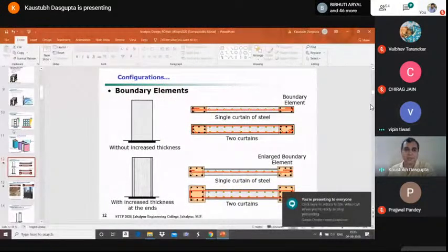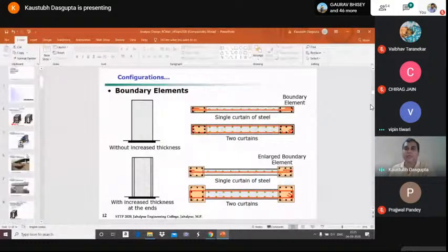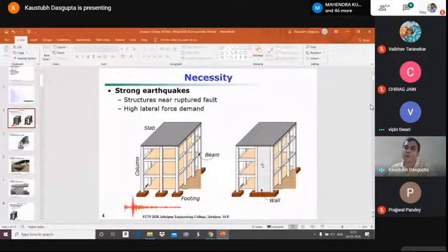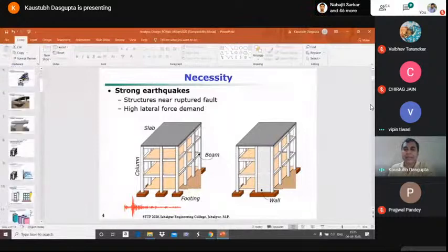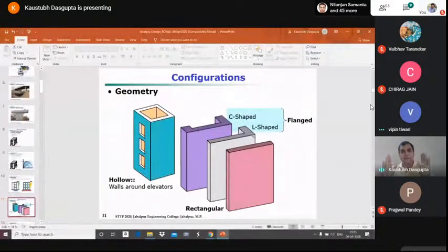Yes, it is beneficial. The first question which I answered, I mentioned that these walls need to be placed symmetrically. So if you want to place at the corners, you can provide the shear walls in this L type of configuration. So in all the 4 corners, you provide L shape of walls. At all the 4 corners, you have walls along width, walls along length. So that's quite good, so that you have symmetry both along the width as along the length.